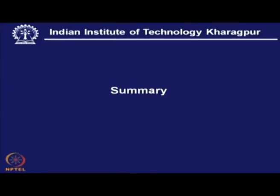So, with this we can make a summary of the discussion that plasma spray is basically meant for all material to be deposited which are having high melting point, and it is mostly the ceramic material. To give some example, it is aluminum oxide, zirconium oxide, titanium oxide. These are some material of immediate interest for engineering use. They can be used as thermal shield and also in many cases as wear resistant material.